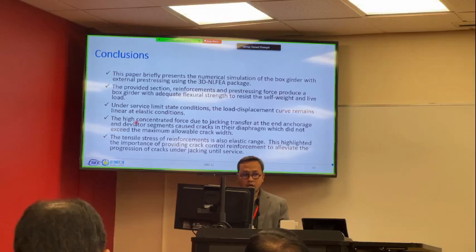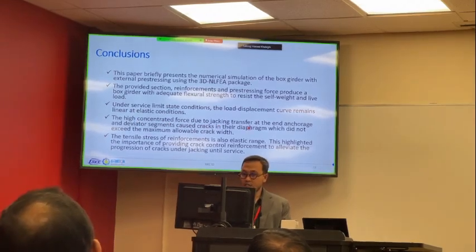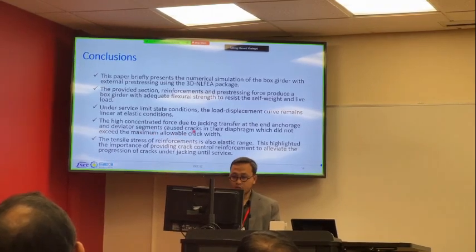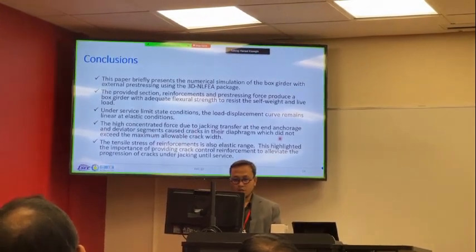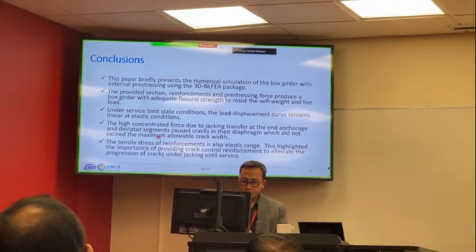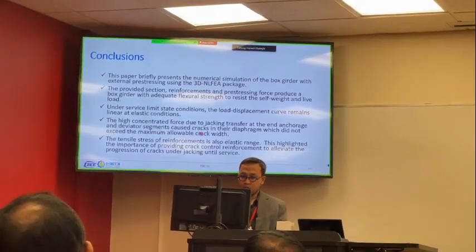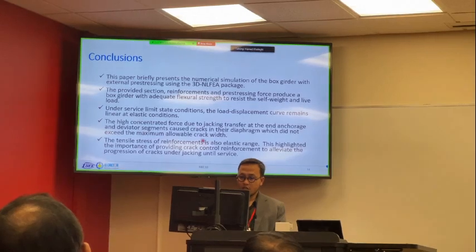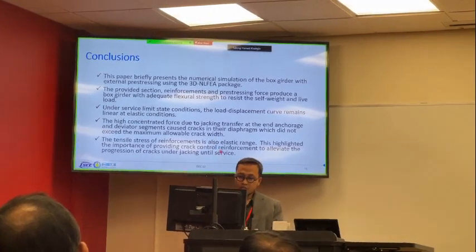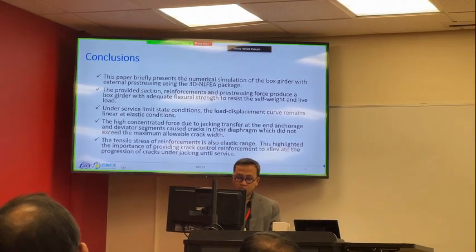And the highly concentrated force due to jacking transfers at the end anchorage and also the deviator segment, causing cracks in the diaphragm. Why? Because the stress exceeded the permissible, but the crack width is in the allowable range. And after that, the stress in the concrete is resisted by the steel.